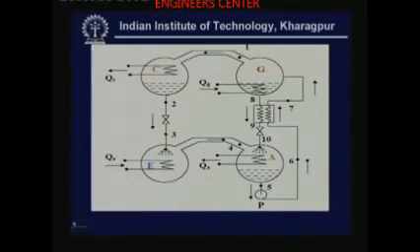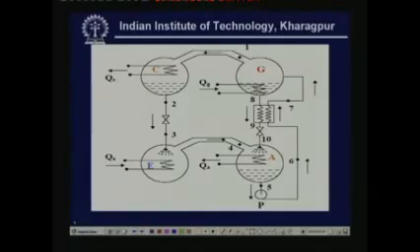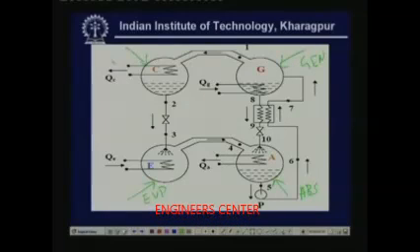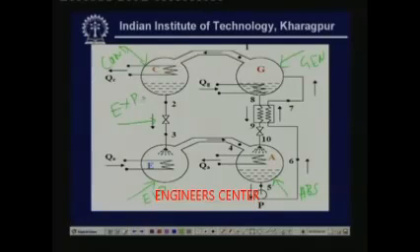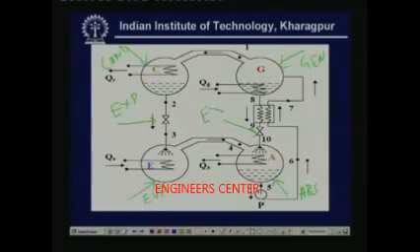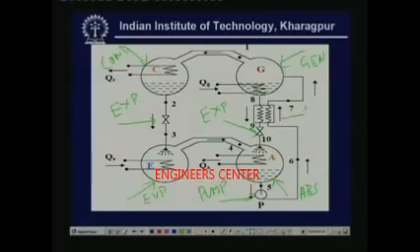Now, I have already explained this while discussing vapor absorption refrigeration systems, but let me once again quickly explain the system and show the various state points. As you know, we have the evaporator here, this is the absorber, this is the generator and this is the condenser. In addition, you have the expansion device for the refrigerant and the expansion device for the solution, you have the pump for the solution and this is the solution heat exchanger.